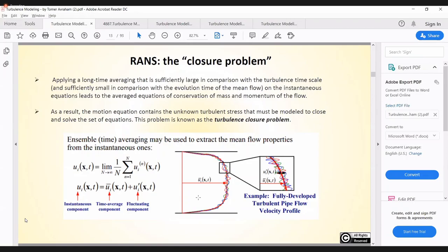Here we don't really have a scale separation. You don't see it anywhere. So it doesn't matter where you put the filter. Besides the resolved scales and the subgrid scales, called SGS, there is a stress which is called the Leonard stress. This is the stress that relates the SGS and the resolved scales. And this one is very important to calculate.